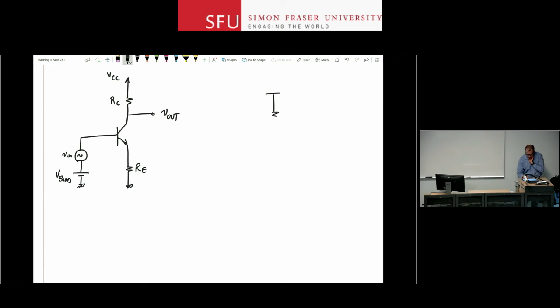let's look at this simple circuit. If I have a diode that is directly connected to VCC, and you're looking at ID and this is VD, the tiniest change in VCC is going to create a huge change in ID because all of that VCC has dropped across the diode. By putting a resistor here, now this resistor is acting as a moderator.